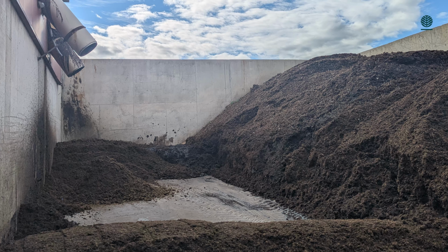After the digester, we have the dewatering. We do it directly after the digester, because if the dry matter content increases inside the digester, we give back the liquids after dewatering directly to the digester. So bacteria are still alive, it's still warm, it's still active, and we only take out used substrate. We take it out of the process and store it beside the digester, or we can truck it back to the silo until the time comes to use it as a fertilizer.